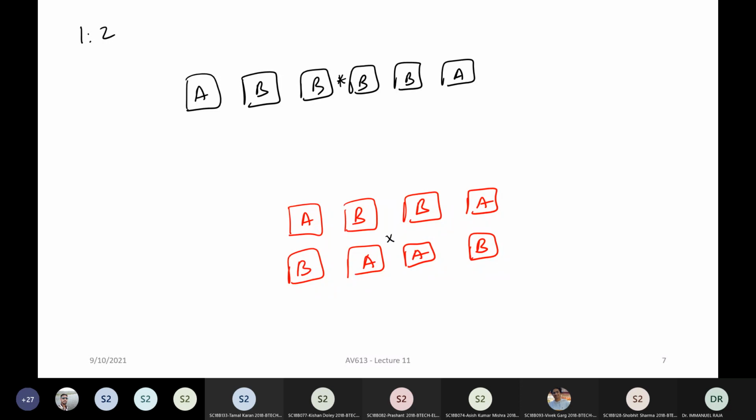Okay. So current mirror layout is usually done very carefully, and you always use unit cells so that each of these boxes that I have drawn are all of the same dimensions, same W and L, and you have to be quite smart in the way that you do it. In fact, it need not be a 2 cross 4. It can be a 3 cross 3, 4 cross 4. Sometimes, when you have so many transistors, it becomes a very big thing. And sometimes you will have ratios like 1:3. For example, if you have a 1:8 ratio, okay.